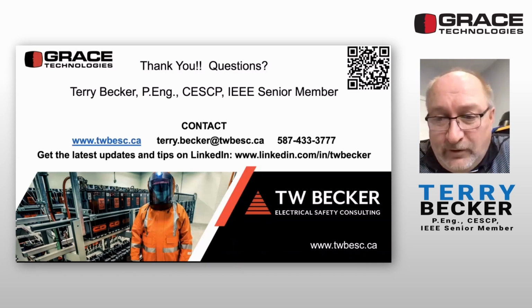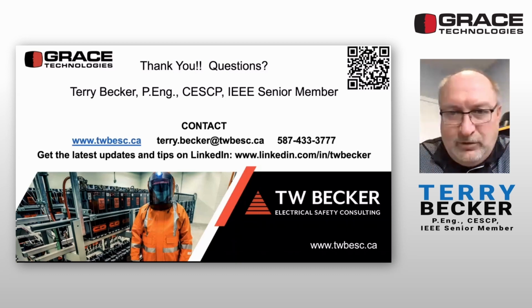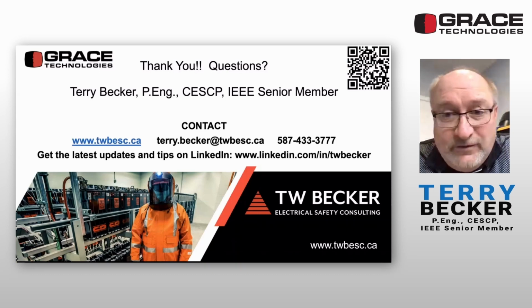It's always been true. Also, if the door doesn't count as protection, then couldn't you technically open the door prior to testing with non-contact and then waive the non-contact? That one's a loaded question a little bit. So yes, opening a hinge door energized is allowed. The problem was in 70E, the need for a permit just to do that, which I tell people, exempt the permit, like a decade ago, for opening hinge doors and even removing bolt-on covers.